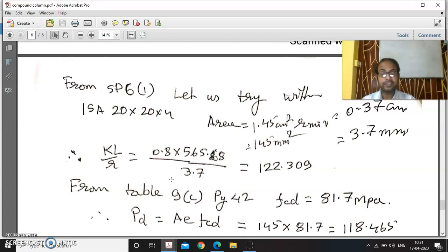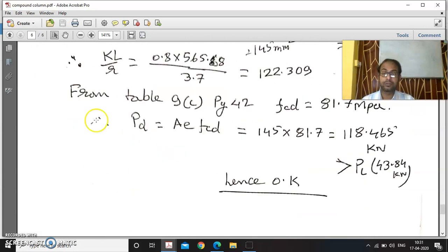The lacing is an axially loaded compression member, and in the design of compression members, we have seen that we can take the effective length from 0.7 L to 1 L according to the degree of fixity. Here the degree of fixity is a bit lesser, so we have chosen 0.8. If it is welded, we may choose 0.7 L also.